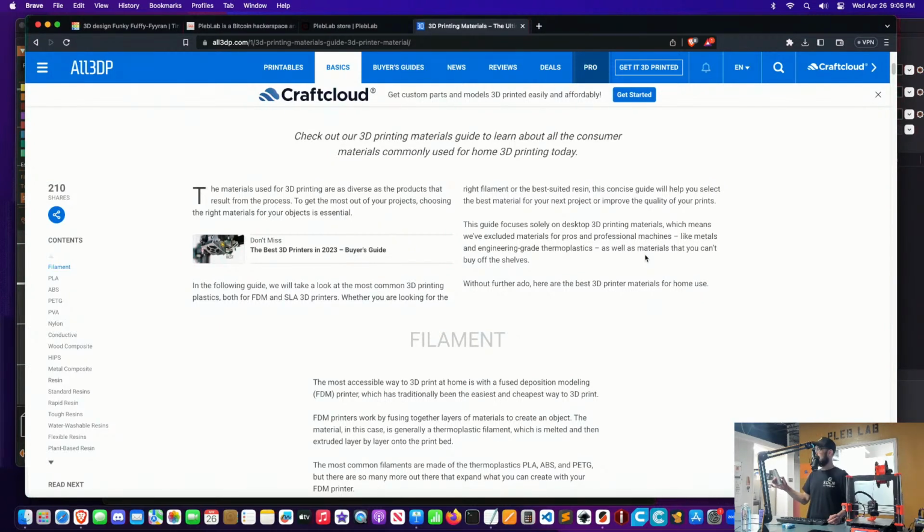But it will warp. Maybe you did a phone clip or something on your dashboard in your car and the sun is hitting it for work, that might start to warp. The glass transition temperature is what we like to refer to. What is the temperature at which the material starts to warp? PLA is around that 80, 85, and that's why I said if you're going to put PLA in the oven, again, stay under that glass transition temperature.